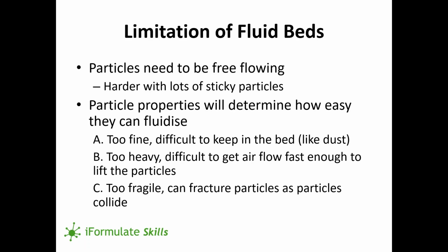However, there are some limitations, as with everything. Particles need to be free-flowing, so it's harder to have fluidized beds with lots of sticky particles. That's not to say that you can't manage these situations. It just becomes more challenging, and you'll sometimes see fluidized beds with vibrating plates on the outside to give the particles that extra kick to break any bonds that they form in the fluidized bed. So that's one way of handling sticky particles.